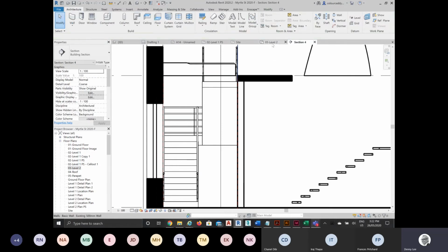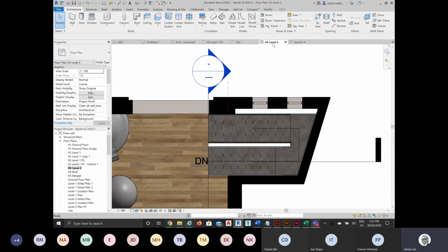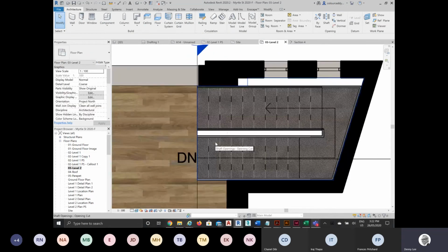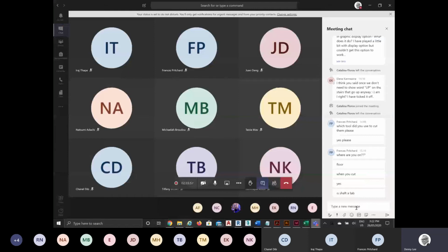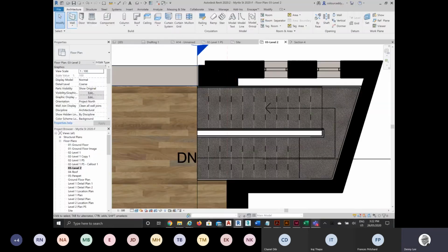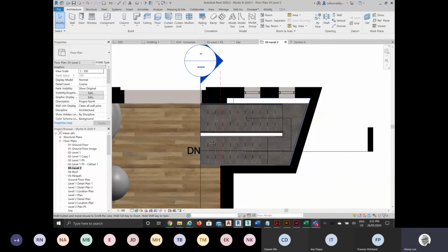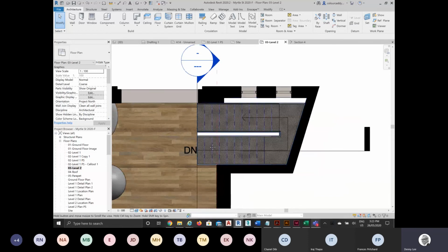You'll often find you switch between several different plans sometimes when you're creating a shaft as well. So a bit like other things like floors and roofs and stairs, it's good to think about the plan you're using to create them. But you can basically use it. Is shaft a tab? Well, it's on the architecture tab. Yeah, so again, under architecture, you have the opening panel over to the right, and then you've got the shaft tool just there. Yeah, so good one to play around with if you haven't already.